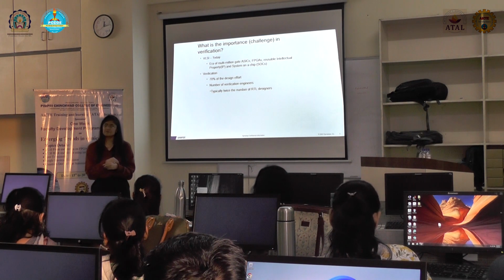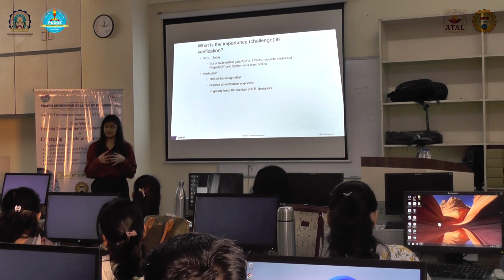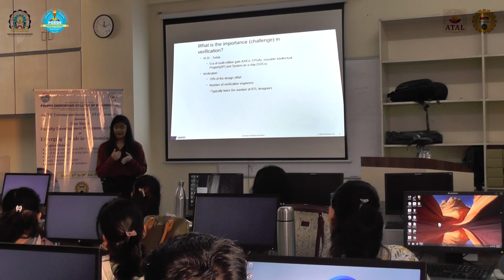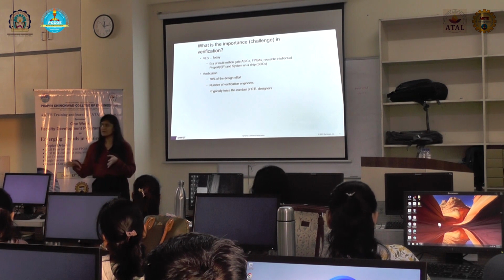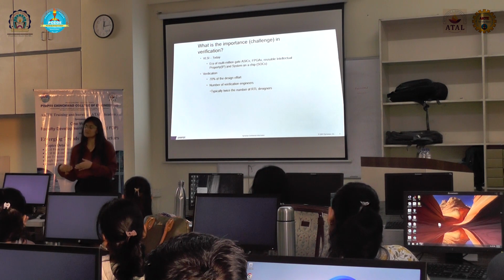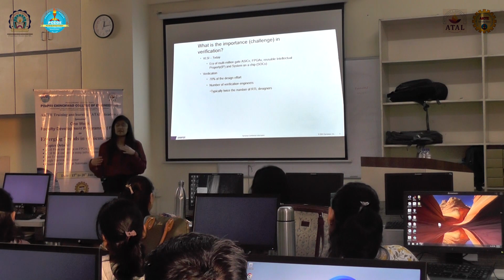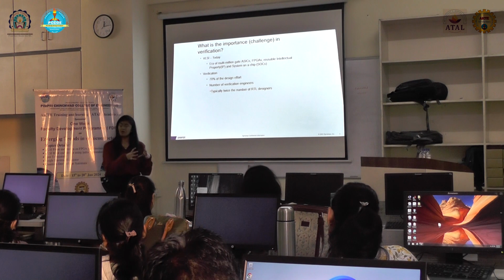That comes down to the individual product, and to the team that is involved. Verification is a very complex and challenging thing to complete. The ideal goal to complete a verification is to collect 100% code coverage and 100% functional coverage. Not only functional coverage, but code coverage needs to be 100% also, because code coverage focuses on the optimized way of coding.